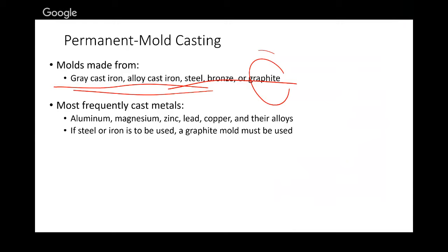So when you're casting something in there, you're going to need to make sure that your mold itself doesn't melt. Okay, so when you talk about these cast metals, these are aluminum, magnesium, zinc. These are going to be lower melting temperatures than, sure, the titanium and these other things that are much higher temperature, so that these can melt while these do not.